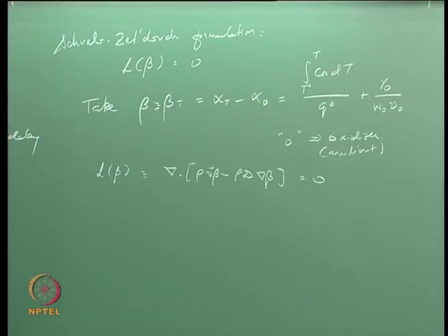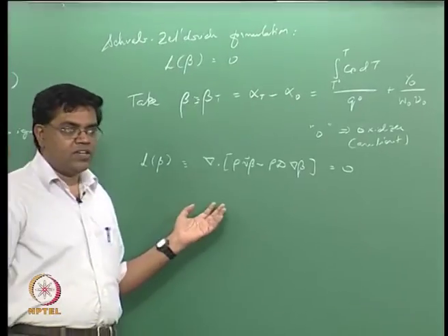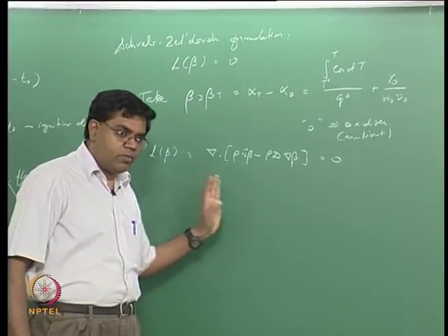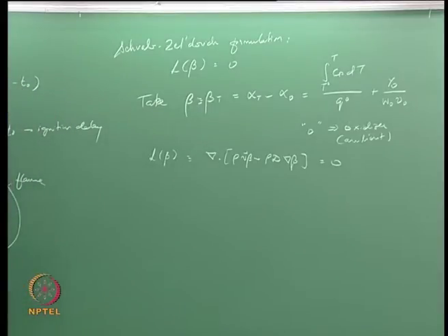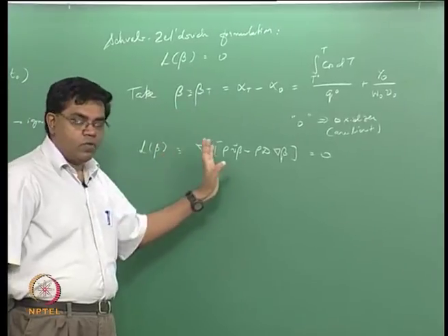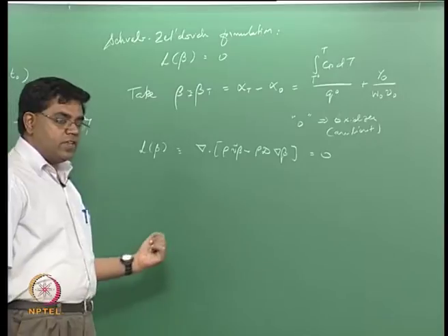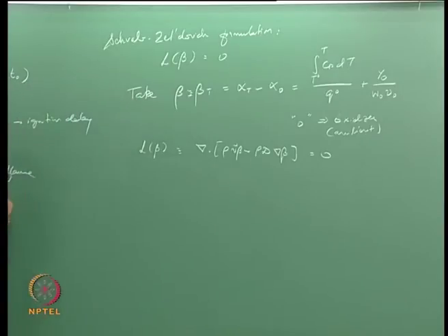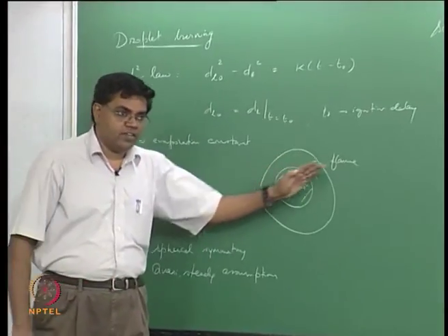In the premix flame problem, we had a one-dimensional formulation, so it didn't really matter; it was essentially one-dimensional Cartesian. In the Burke-Schumann problem, when we adopted the Schwab-Zeldovich formulation, we wrote it for a two-dimensional cylindrical polar coordinate system. It is now going to be back to a one-dimensional situation, because the only variation is along the radius.